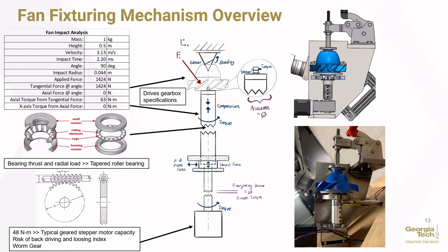Here you can see the setup, calculations, and load set that the main fan axle will experience during testing. You can see highlighted above the forces that the shaft will have translated into it by the fan impact, and how those forces propagate into loads at different locations.